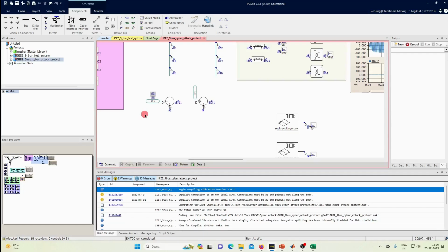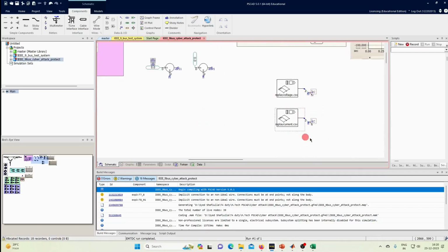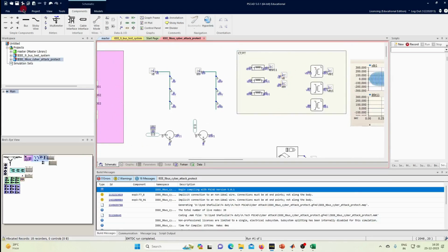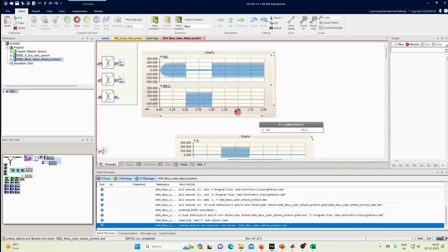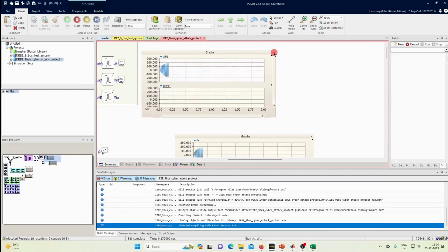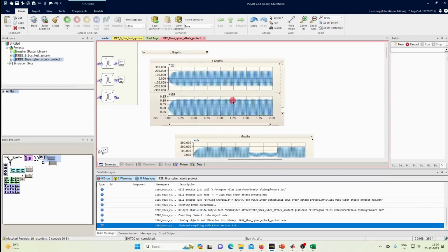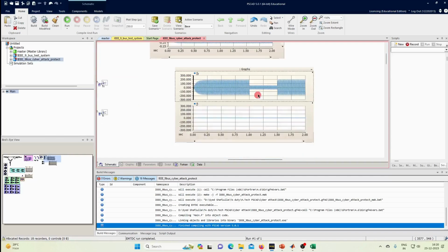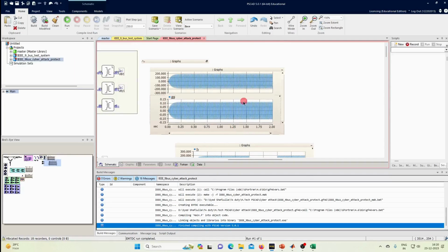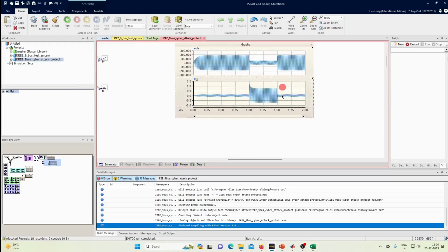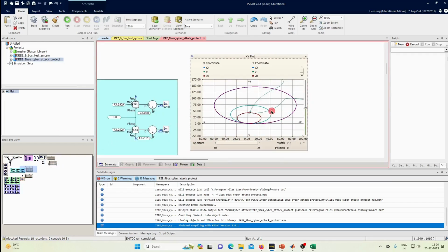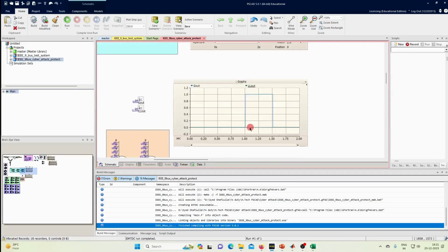Here during the replay attack, we are only taking the faulted voltage and faulted current and feeding them into the system. This is the actual system voltage and current, in normal operation. But due to the replay attack, the relay is seeing the waveforms in this fashion. So the relay is not differentiating between what is actual and what is the cyber attack. We can see the same false signature as last time, and the relay is going to give a trip signal.